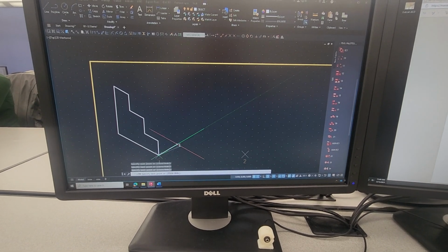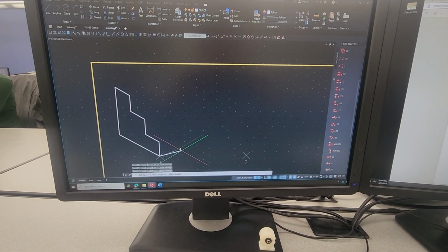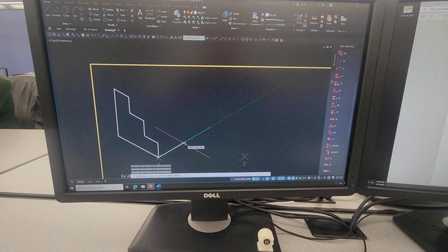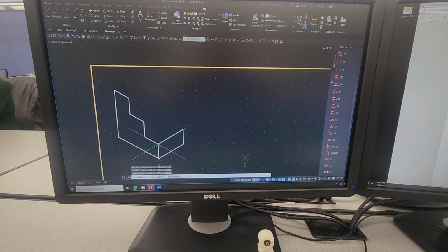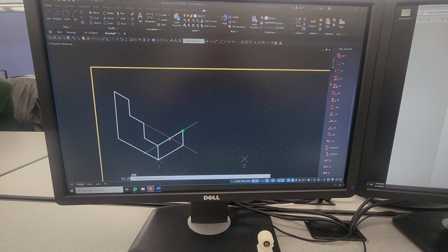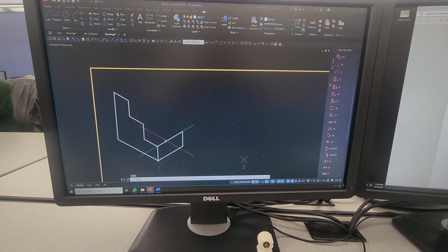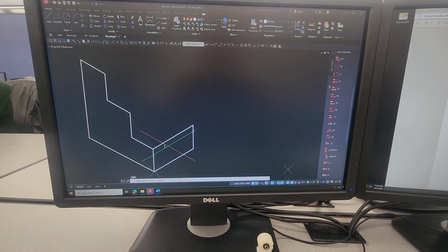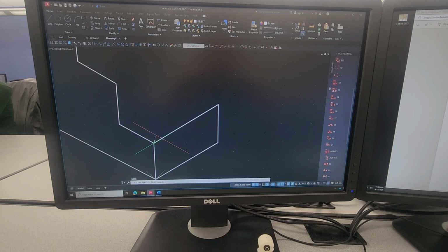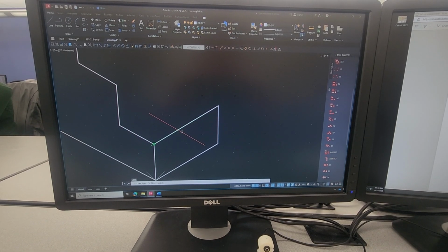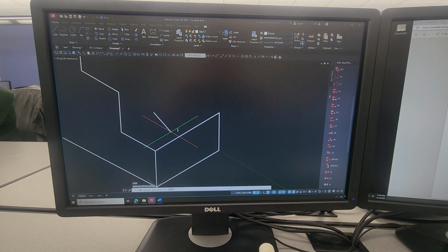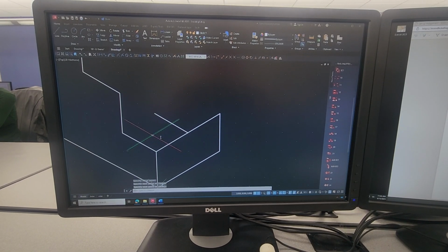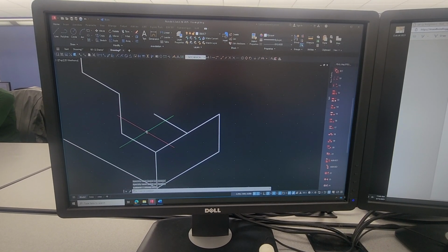Now I can continue to go back here as well. So I can follow counting the grid spots this way too. Now it does jump around a bit, may drive you a little nuts, but you see how I'm just using this, and I can start wherever I want. Oops. Now notice right there, you see how it's grabbing the end point? You ever see that? So I can't go to where I want to go? Okay, I've got 2 choices here. I can go to here and I can go to there, and that'll give me what I want. Or I can just hit F3 and that turns that snap off.